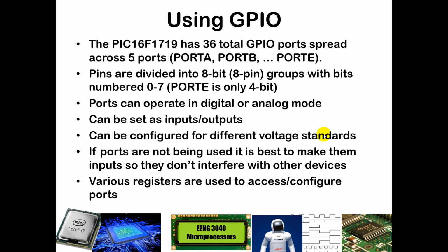Ports can be operated in a digital or analog mode, and even within a particular port, let's say port A, you don't have to make all of those pins inputs or all of those pins outputs. You don't have to make all of those pins analog or all of those pins digital. Because they're nice and general purpose, you can mix and match. So you could make RA0 through RA3 all inputs, and then make RA4 and RA5 outputs if you wanted to do that. You could make RA0 operate in the analog mode, and you could make RA2 operate in the digital mode. And so you've got a lot of flexibility about what each pin is going to be used for.